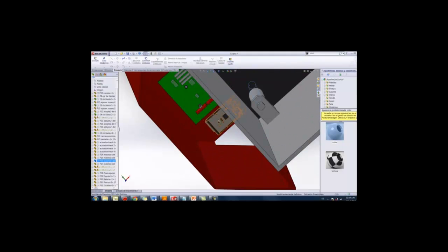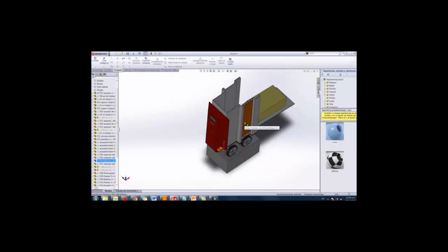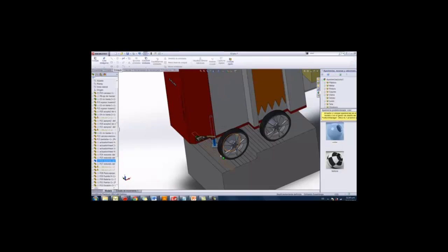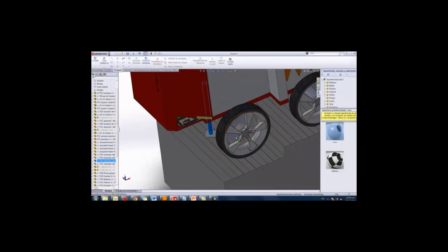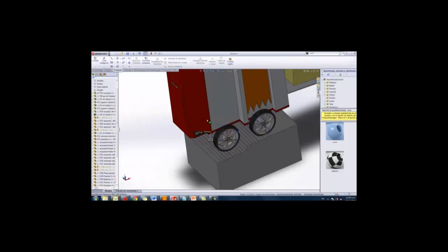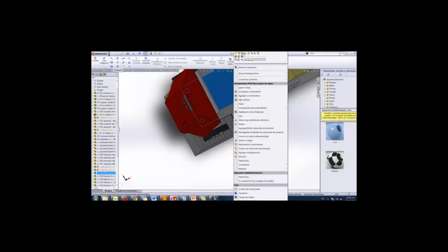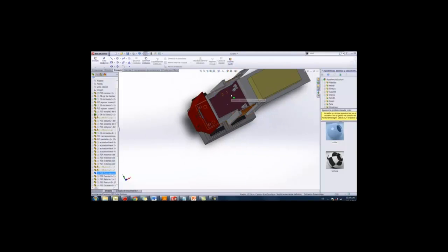The control part is shown at the bottom of the CAD model. It will consist of an Arduino Mega board with a battery and an H-bridge as a power stage. In the tires, we have brake discs, now active in the video. On the top, finally, there is another motor for steering the whole robot.